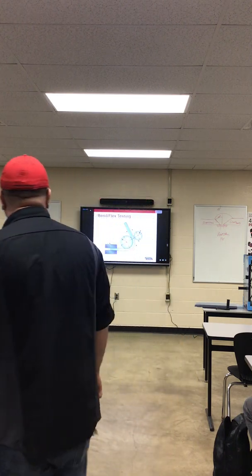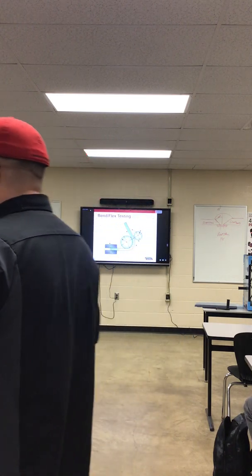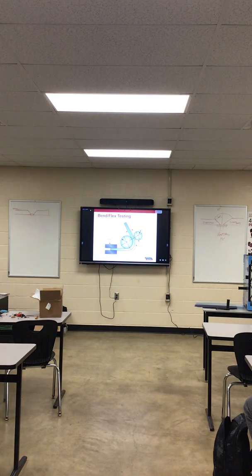Bend flex testing. This type of testing, they're actually clamping or fixing the test piece and forming it around a stationary roller. Whereas we're pushing our side bend or our face root bend through a set of rollers.